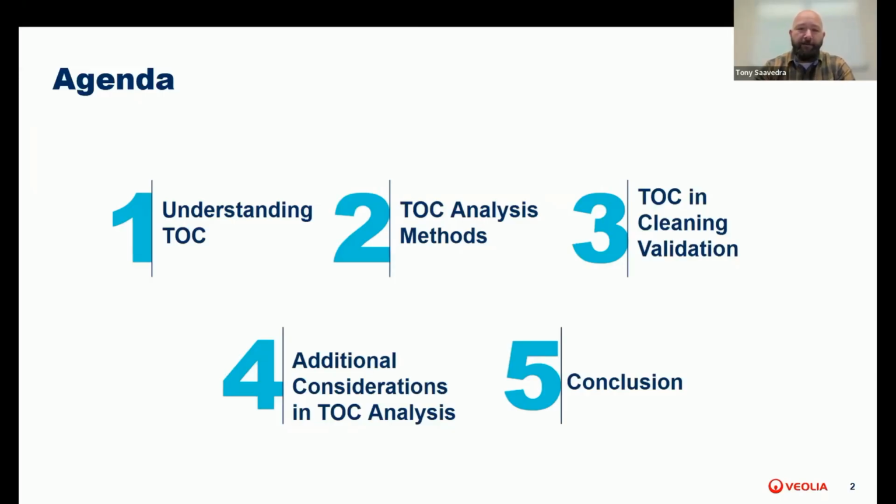One of the applications for TOC in pharma is cleaning validation, where TOC plays an important role as a non-specific method and is used to determine the overall cleanliness of a system versus specific methods. We'll look at different analysis methods to measure TOC to help understand which is the right method for your application.